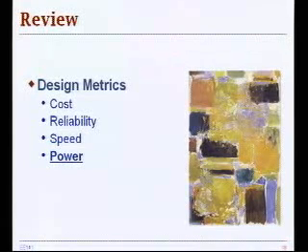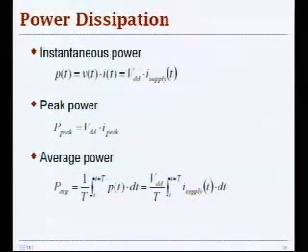Okay, so now we are going to introduce the final and the most important metric in today's designs, which is power consumption. So power actually tells you two things. It tells you about the amount of energy that you store on the load capacitances and also the amount of power that gets dissipated as heat. So it's those two things.